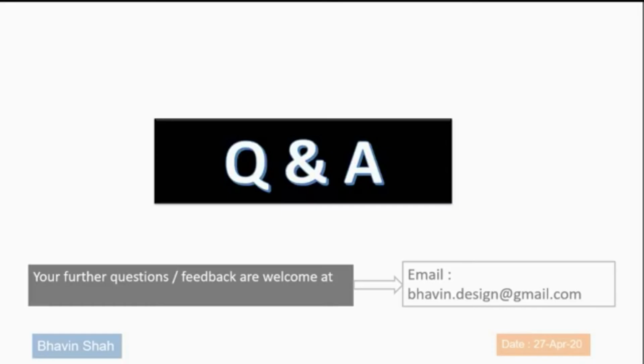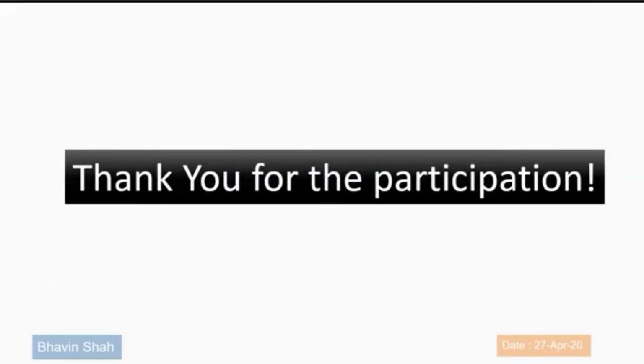Thanks, Dushyant. So Udit is asking that in design of pinned bases, 1.2 times shear capacity of column should be considered for design of anchor bolt. So shear capacity of column should be calculated considering the web area only, or web plus flange area. I think you may include the flange area also, but the majority of the shear is taken by the web portion only. So I think it will not matter much in your final outcome, in my opinion.